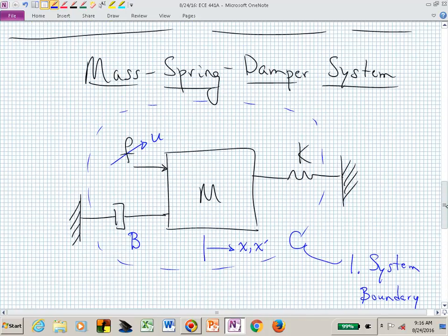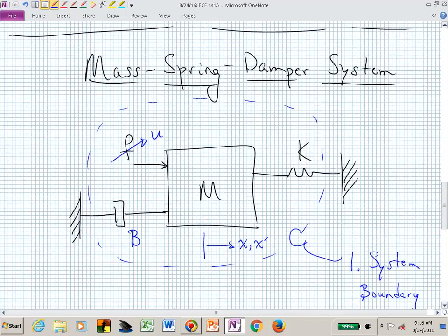If we did the same with the damper, this is something you can think of as a shock absorber that doesn't have a spring, it just has the ability to extract energy from velocity. So really a shock absorber is sort of a combination of a dashpot and a spring in a vehicle. Here we're extracting those two and looking at those independently. So we have a spring.